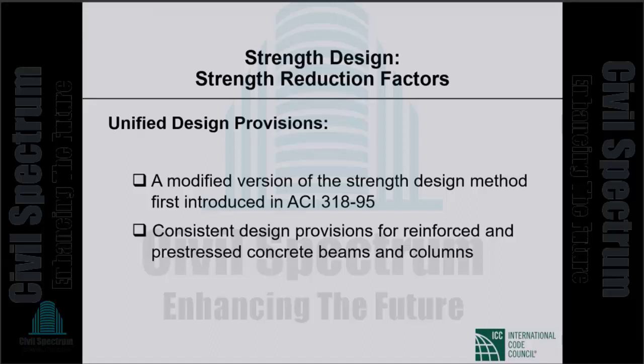Also, pre-stressed concrete and reinforced concrete should be viewed as two extremes of a continuum, which is partially pre-stressed concrete. You can combine reinforcing steel and pre-stressing steel in the same member, and depending upon how much of the load effect is resisted by the pre-stressing steel versus reinforcing steel, you can have behavior approaching that of a reinforced concrete member to behavior approaching that of a pre-stressed concrete member.